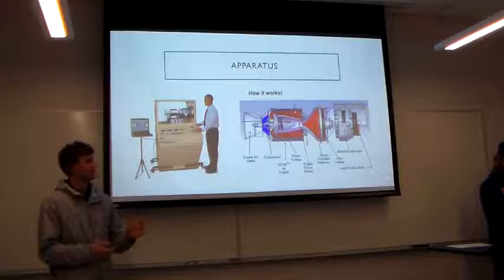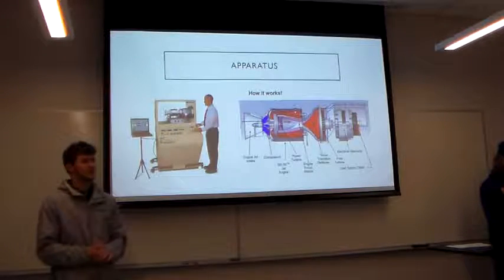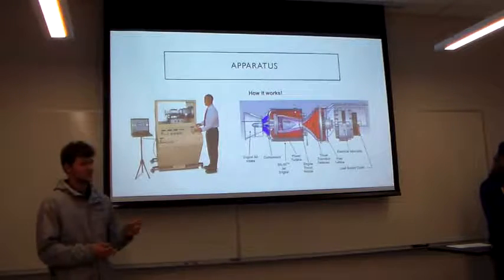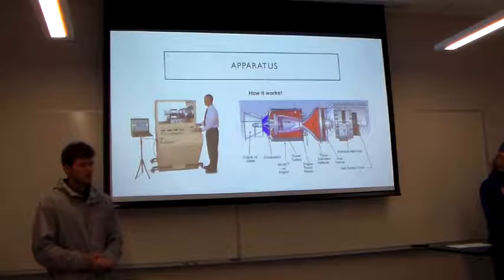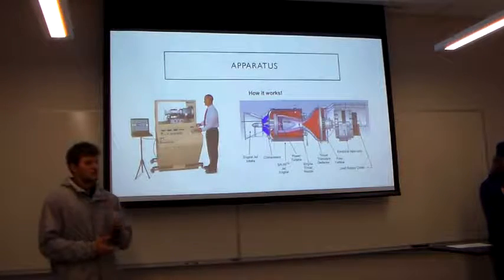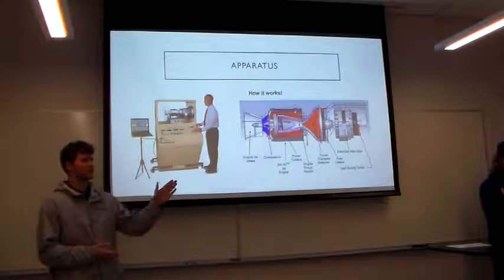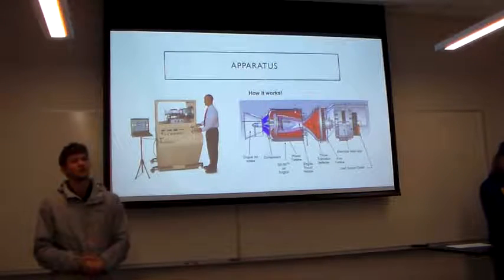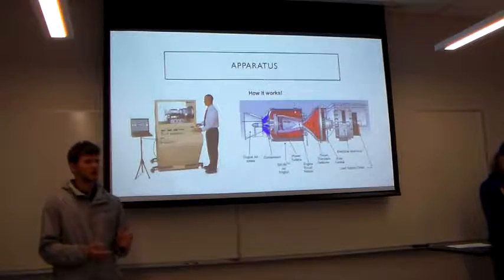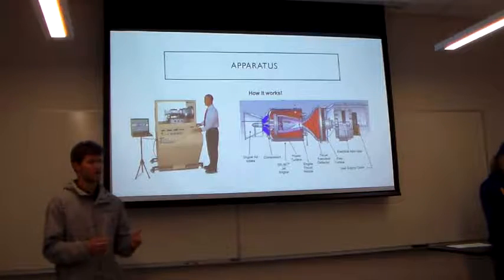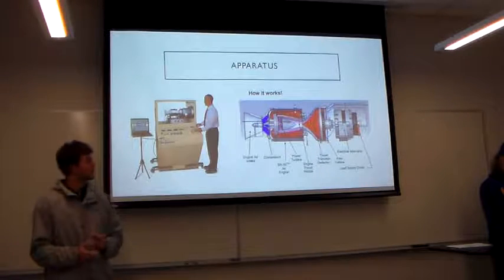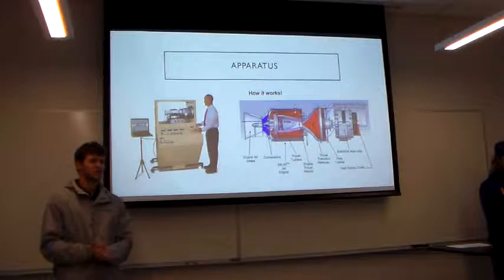So the nozzle takes the air that just got expanded through the turbine, and expands it a little more, and creates a jet of air. And this jet has an associated kinetic energy and momentum with it. And this momentum is what, by reaction force, moves your aircraft or your missile forward. But obviously in this case, that's not what we're after.